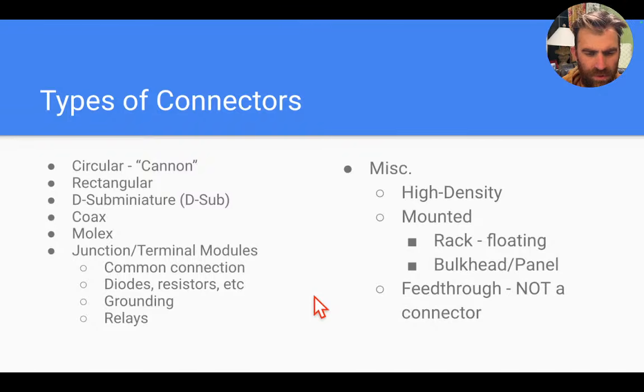And they're basically like modules that you can insert the different wires in after you terminate them, put a contact in them, and they go into the module itself. So it provides continuity between several wires. So it's just like a common junction point for the wires.